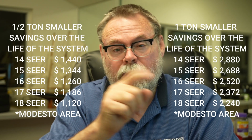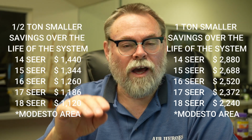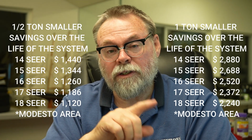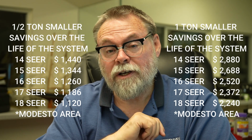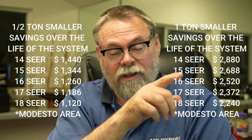It's very, very important. Please, if you don't do them, start doing them. I think you're going to be surprised, and you're going to have much happier customers because the unit's not going to be oversized, not going to be cycling as much, and she's going to save herself a ton of money in the long run. Over the next 10, 15, 20 years, she's going to put money in her bank account. Do yourself a favor. Do the customer a favor. Do load calcs on every house.